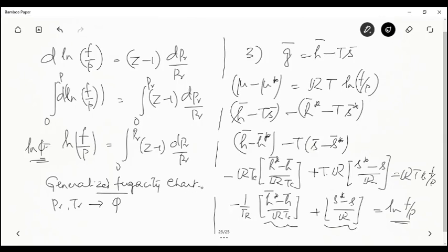So given the value of temperature and pressure, I'll be able to get the fugacity from this. So we have now defined fugacity for a pure substance and understood how to obtain the fugacity of a pure substance from the charts of generalized correction, either the generalized fugacity chart or the generalized enthalpy and entropy correction charts. So at the moment we'll take a pause here.